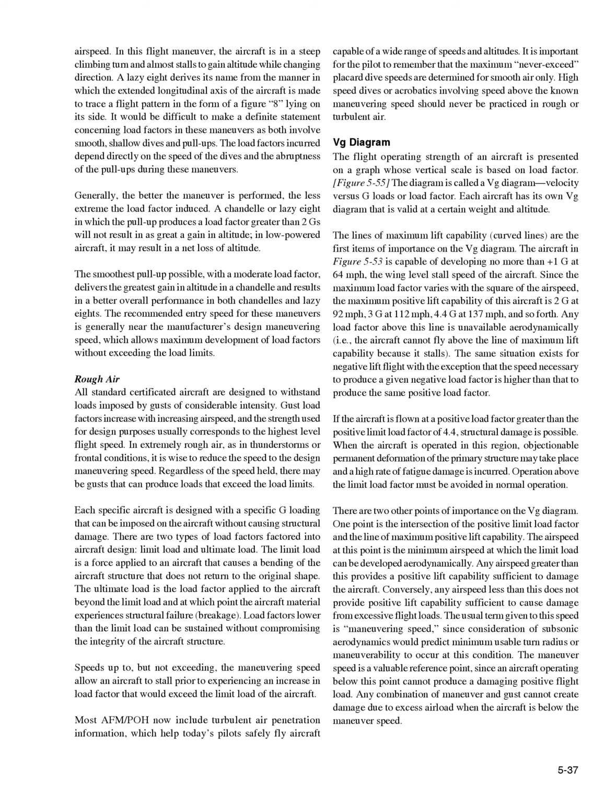It would be difficult to make a definite statement concerning load factors in these maneuvers as both involve smooth, shallow dives and pull-ups. The load factors incurred depend directly on the speed of the dives and the abruptness of the pull-ups during these maneuvers. Generally, the better the maneuver is performed, the less extreme the load factor induced. A chandelle or lazy eight in which the pull-up produces a load factor greater than 2 Gs will not result in as great a gain in altitude.